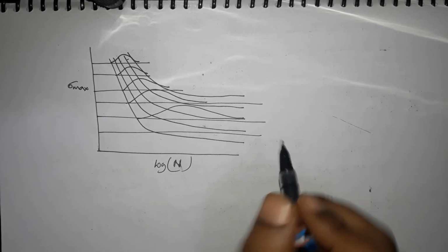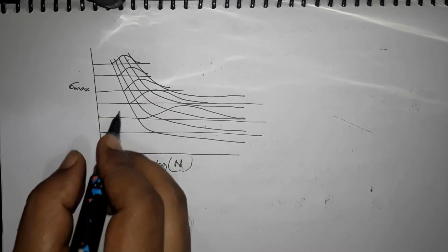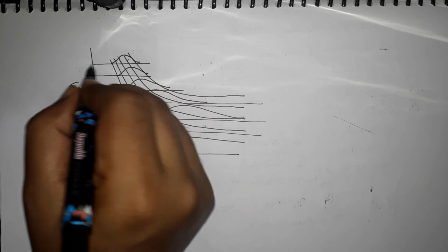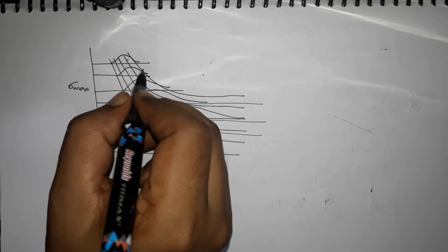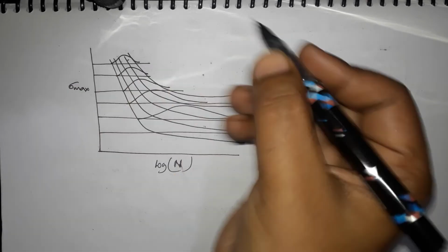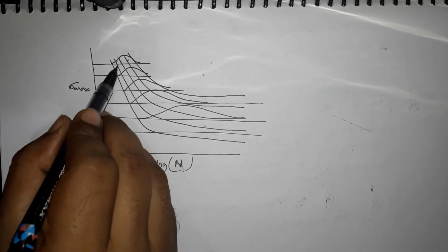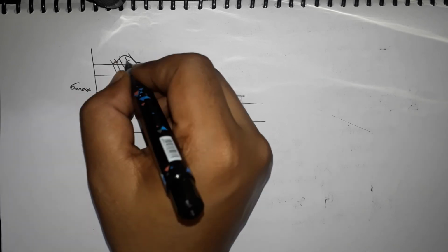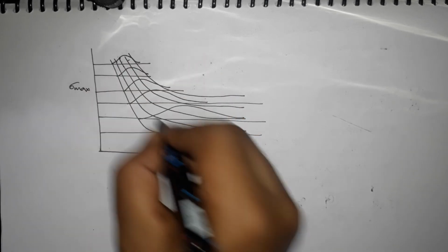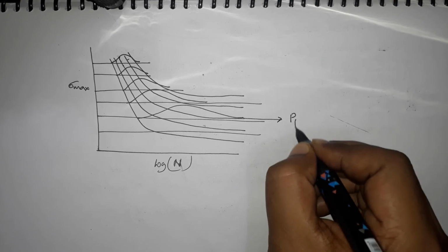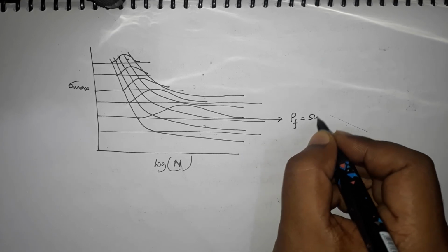Okay, so instead of defining one SN curve, what you can do is, let's say, 20 tests at each stress level, and then you define some probability and plot the probability curve for 50%. So let's say this central line is the line for probability of failure of 50%.